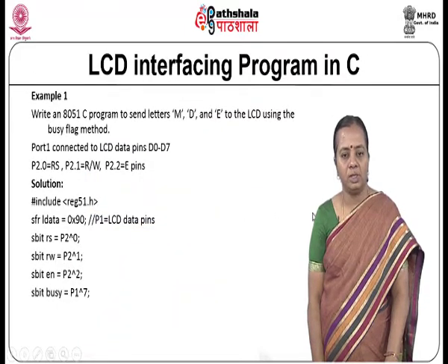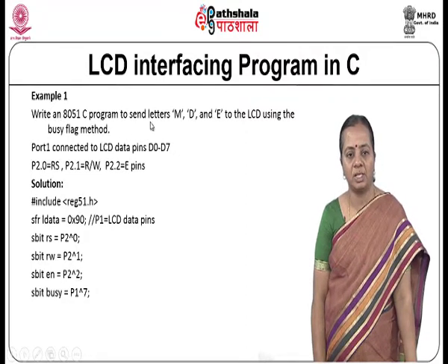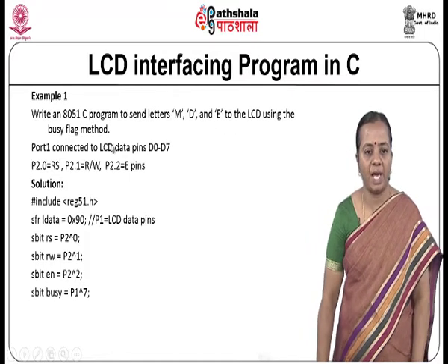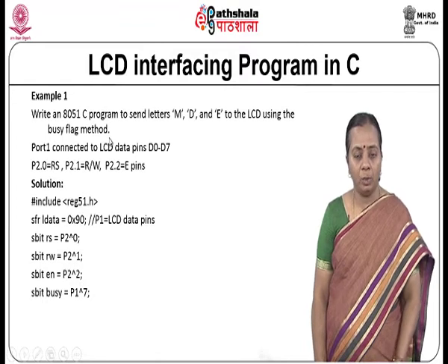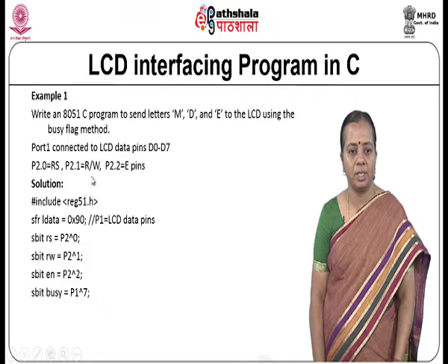Now this is code which shows how to communicate with an LCD to display certain things. This example code sends the letters MDE to the LCD using the busy flag method. That means we will check whether the LCD is busy or not by looking at a pin.